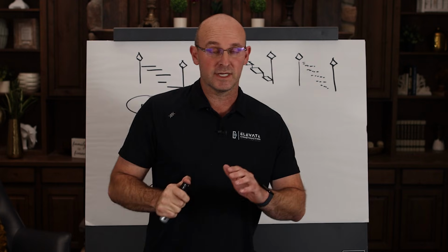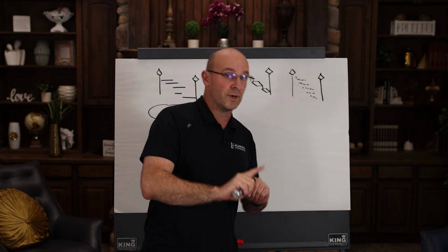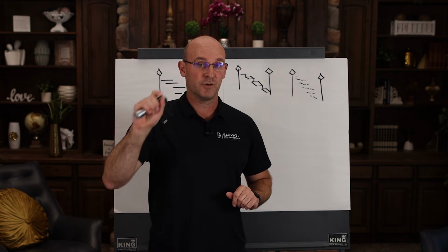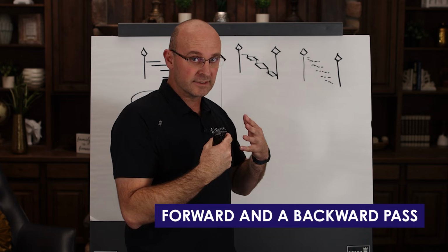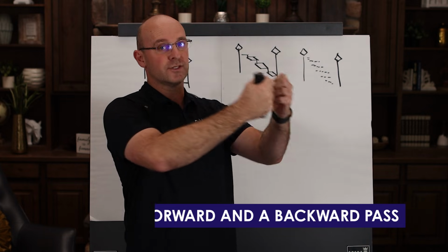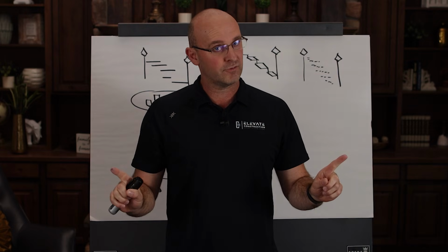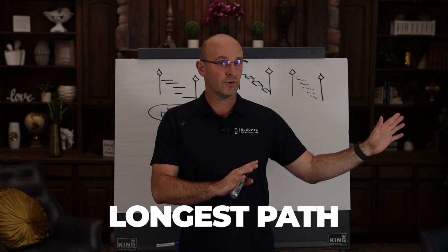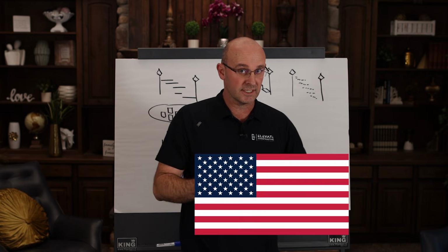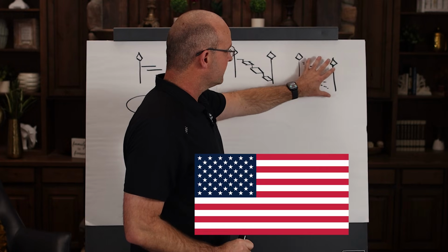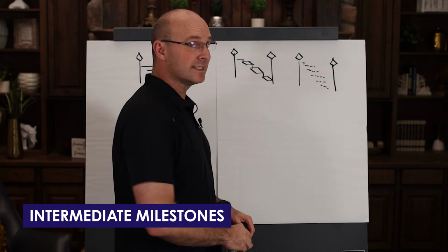And I'll tell you why, because the critical path method, according to the rules and what you will get audited by and how the industry uses it, and per the exact definition, will run a forward and a backward pass. And what it will do is put things to its earliest start, and the critical path will not have float and it will not have buffers. Now, a longest path can have float or buffers, but the critical path method, the way it's used in the United States, is very toxic. And most of the time you will not be able to have those intermediate milestones be set properly.